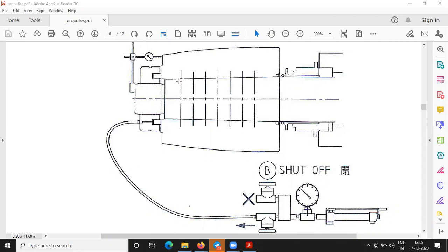Get it? And how will you know whether any dirt is there in between when you're doing this check, sir? First you have cleaned it, now you are fitting it. Yes, sir. So according to you there is no dirt, because you have nicely polished it, and you have used acids to clean all the oily things, roughness, grease, everything. But if there is anything, like when you are fitting, some wind may blow and some dirt can come in, you will come to know when you draw the graph. That is why I'm saying this point of the deflection in the pressure gauge is very, very important.